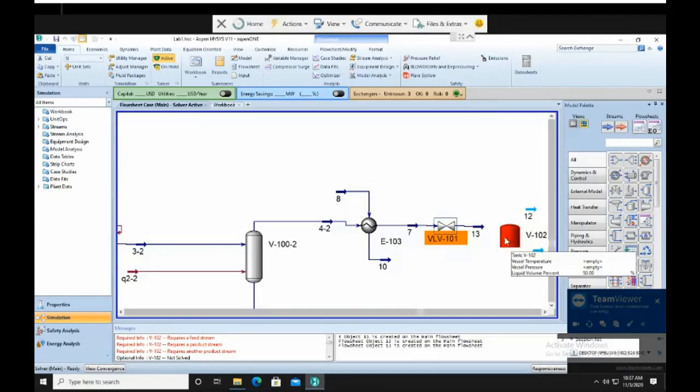So that you can keep the temperature in here at 10 degrees Celsius, but you still have to supply coolant to the tank. Unless you want to store it at higher pressure, so you can actually store it at probably 25 degrees Celsius so that nothing will be evaporated. So you have to make some economic evaluation.